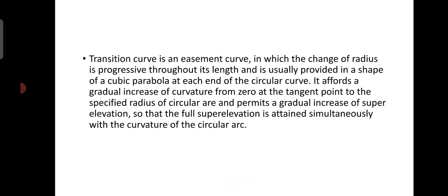Transition curve. A transition curve is placed in both railways and roadways before approaching a curved path. It gives a gradual transition from a straight railway track into a curved portion. The transition curve will be straight at the start, and its curvature gradually increases until it reaches the same curvature as the curved track when it approaches the curved path.